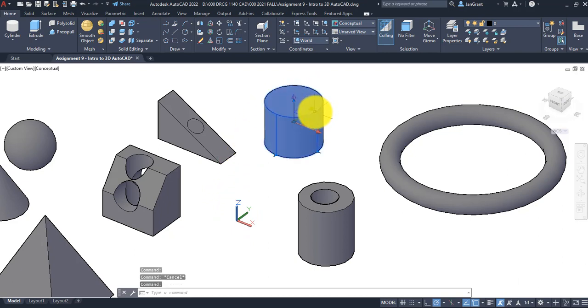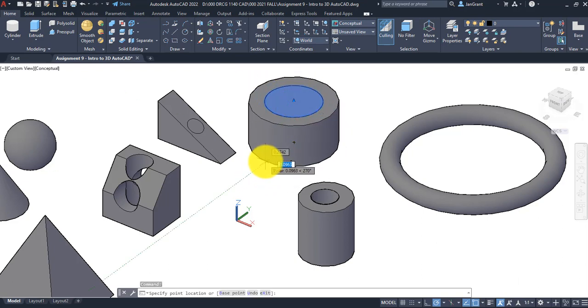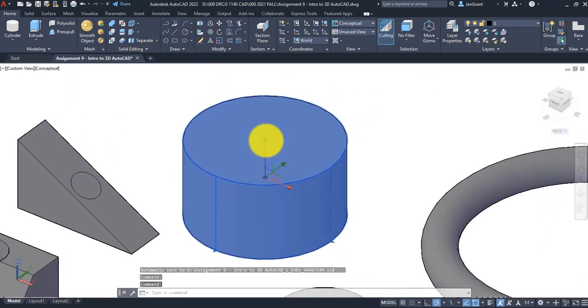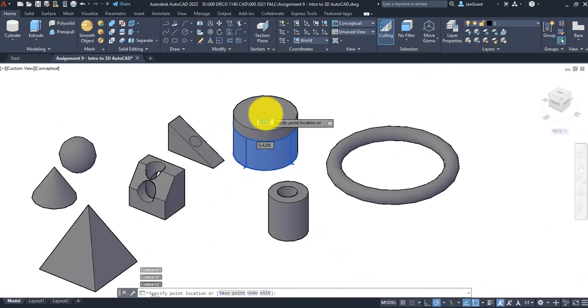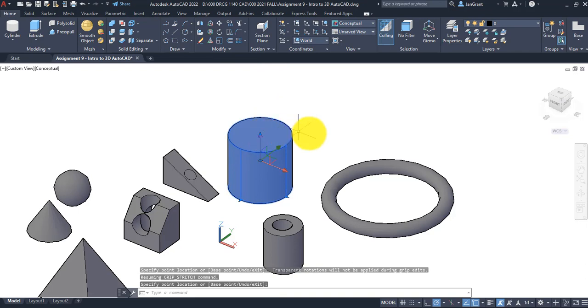So if you need to draw another cylinder or another box, go ahead and do that and then select it and notice that you have these little blue triangles on the bottom that you can click and change the radius of something that you've already drawn. You may have to get up pretty close to get that top triangle grip to make the height a little bit taller.